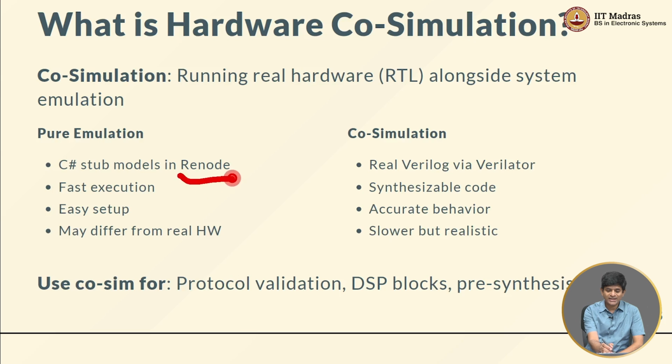Now the Renode code itself is written in a language called C#, which is related to C and C++ but is different in its own ways, but has all the same kind of behaviors. In particular, it compiles down into native executable code, which means that whatever stub you are writing over here will execute very fast. And we have already seen examples of this. For example, the Renode REPL files, the platform files, have things called UART, timers, and various memory blocks, which we used to create a fake smart timer and a fake FFT and so on.